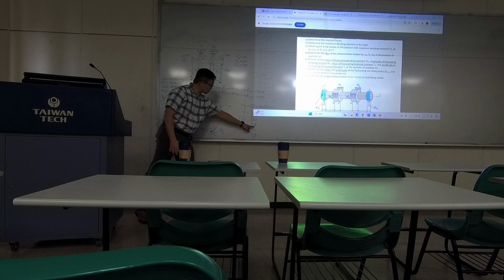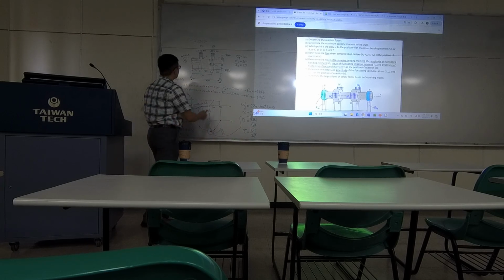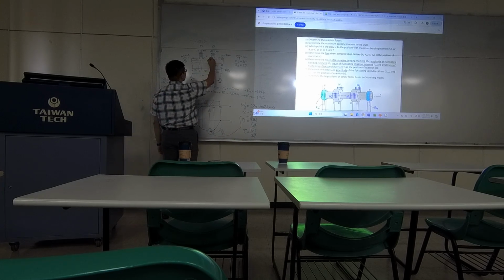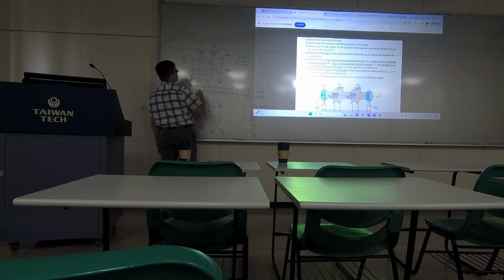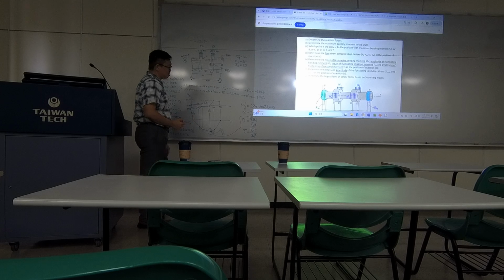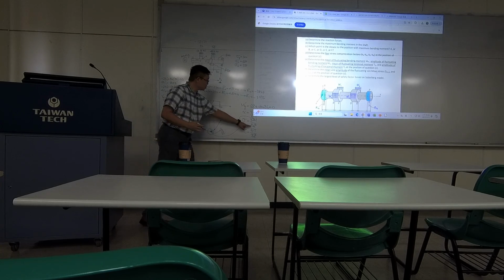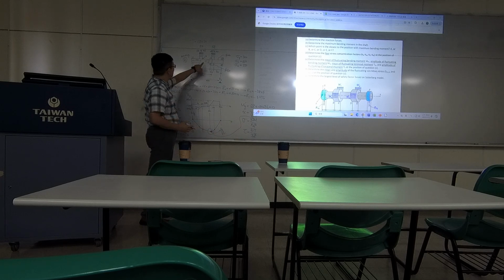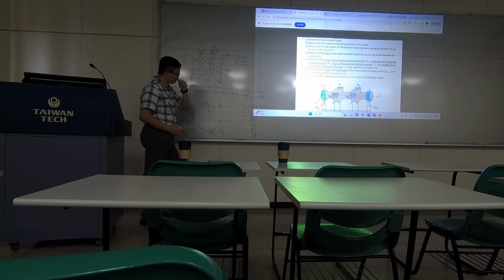And for the small d right there, you need to use the critical diameter. You need to use the small d, not the big one. That's how you can get the worst stress condition. So this small d would be the small diameter right there, so that would be 40. Okay, so plug in all the numbers.